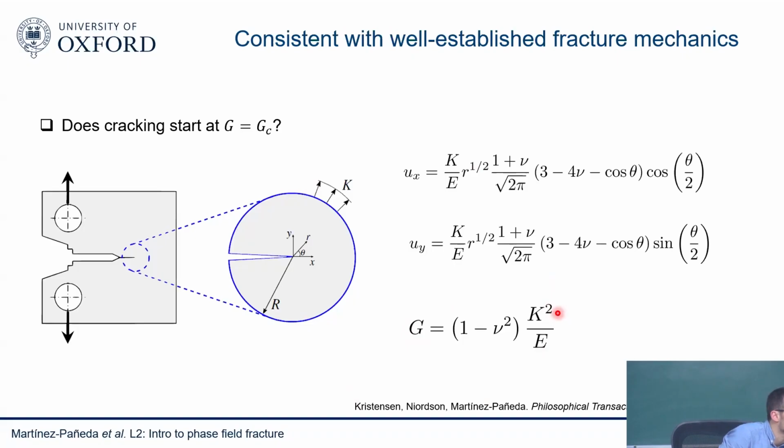When you keep on increasing, the K field is not applicable on some sides. That's correct. So what we discussed before, if you have, here I'm just looking at linear elasticity, so it will always be applicable. If you have an elastoplastic material, you could have some edge effects, I guess, depending on the size of the sample. If you have an elastoplastic material, eventually the plastic zone will be so large that your K field will become invalid. What are the first terms of the infinite series of the Westergaard's? Yes, so you have a T stress and other things as well. You could actually add them if you wish to. You could have a constraint effect, for example, with a T stress and so on. But in principle, this is the dominant term of the Westergaard series.